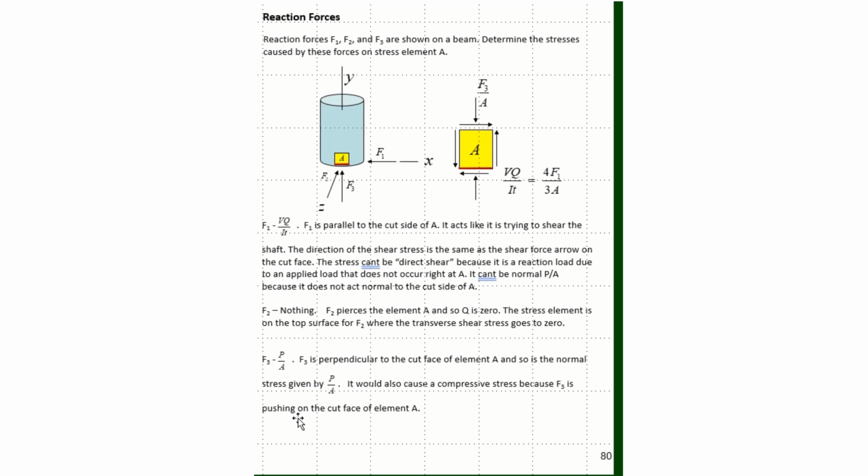We then looked at this example. Well, before we went to the next example, here's a summary of how to treat the forces. So these are reaction forces. So assuming that this body was loaded somewhere such that we computed these reaction forces, this is how these reaction forces would cause stress on element A, where element A is on the front of this cylinder. Element A is positioned on the front of the cylinder.